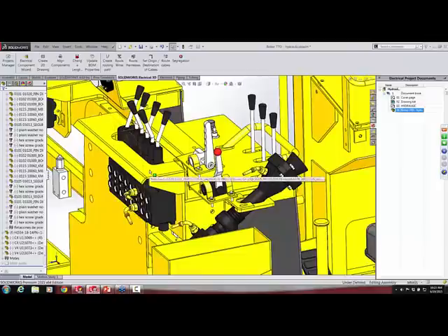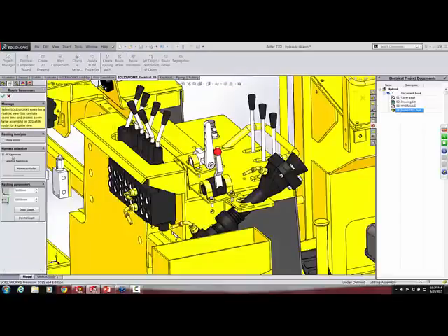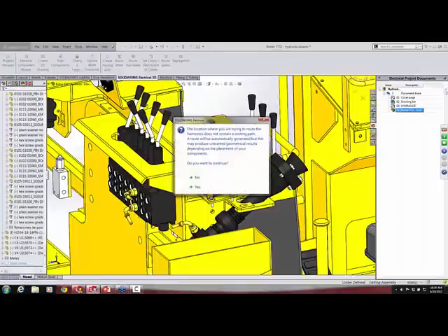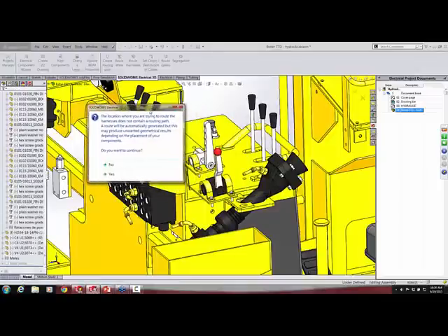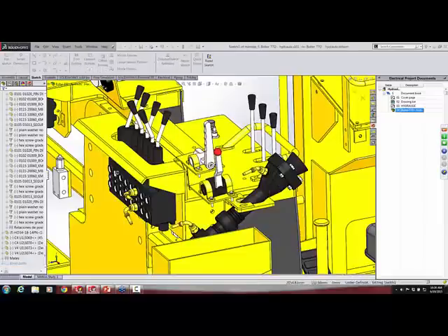Now if I go back to SolidWorks, I can route harness. And I'll route all harnesses, or I could individually select them and route them individually. Now, electrical, if you're not familiar with electrical, you can create something called EW paths. It's in effect a 3D sketch. And that 3D sketch is used to route wires the way you want to and not automatically route them from point A to point B and go through stuff. Here with hoses, I want to continue. I'm going to go ahead and just use the auto route capabilities.